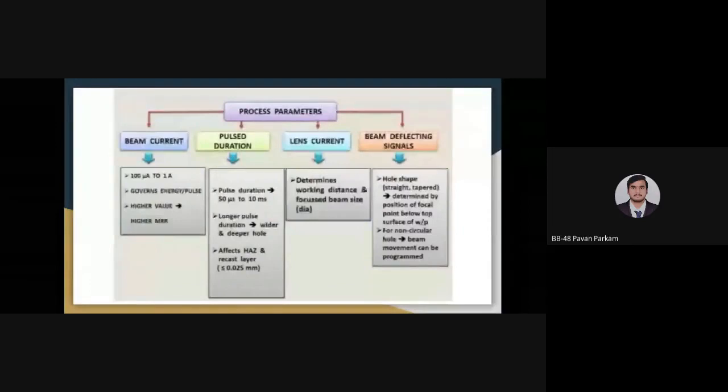Now, second, pulse duration. The duration of the pulse varies from 50 microsecond to 10 millisecond. A longer pulse duration will generate wider and deeper holes. If we apply the pulse for a long duration on your workpiece surface, obviously it will generate wider and deeper holes.